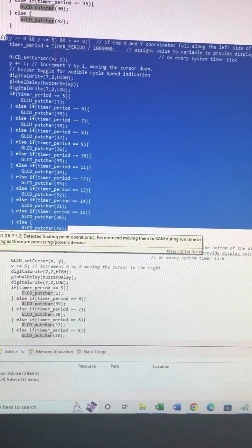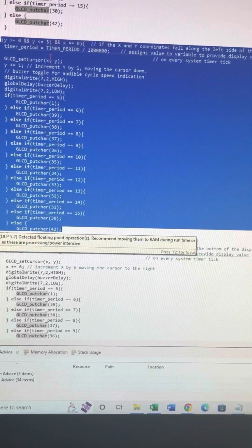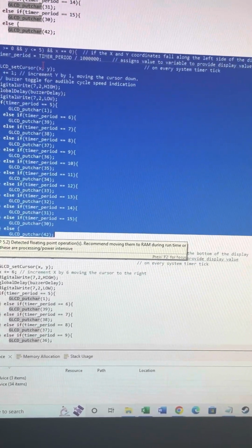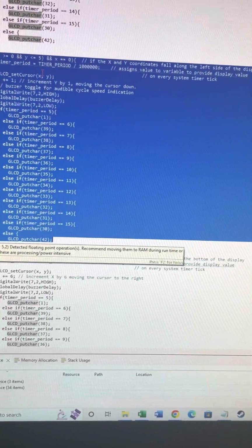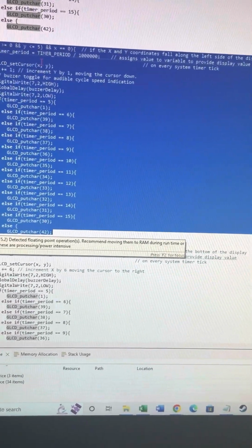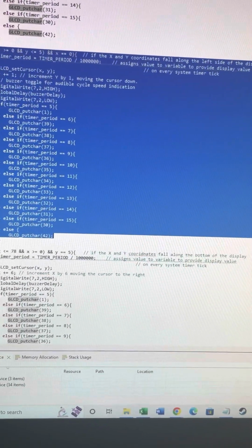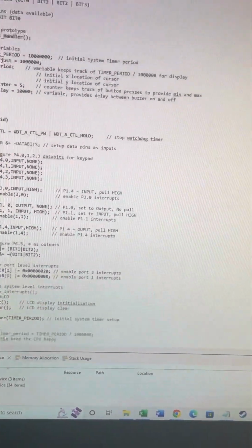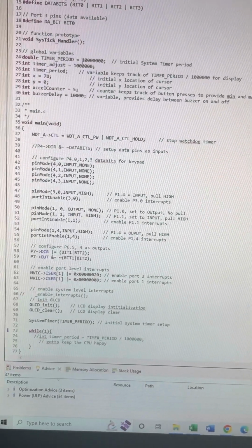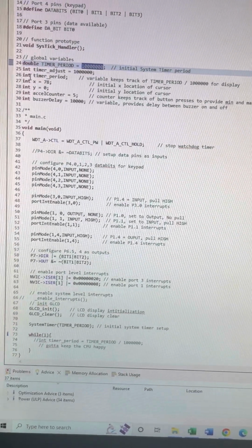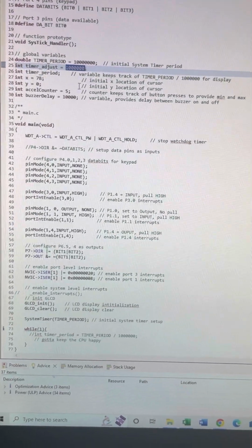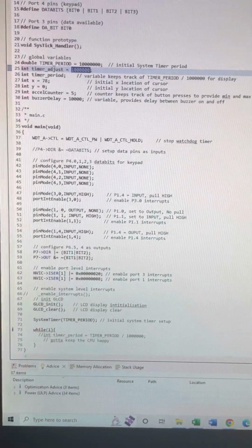For instance, if I wanted to send out a voltage on some port to a base junction transistor that's an on-off switch for some kind of motor circuit, I could do that. And by manipulating this timer period, which is the initial timer period, and then this timer adjustment, you can change how quickly it will cycle.